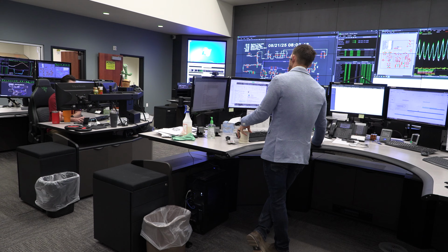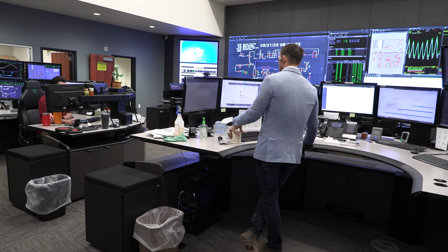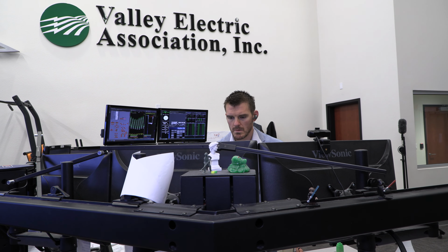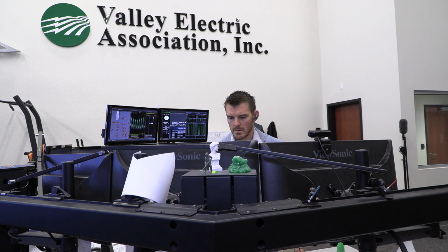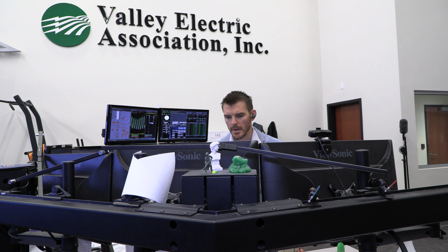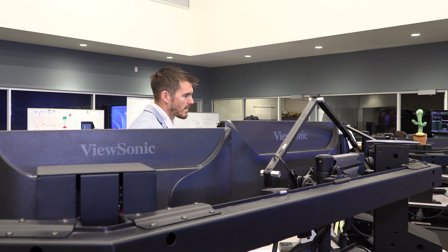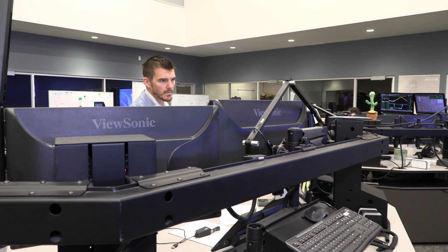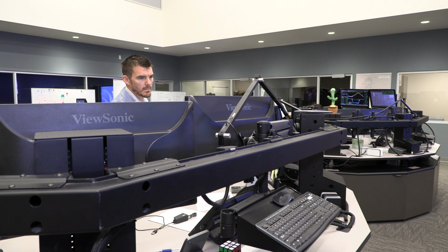It's separated in the fact that it has different outage severities. If we have a transmission outage, it's likely going to be more severe than a distribution system outage. If it's a very severe transmission system outage, it could encompass a lot of distribution that's out. A bad enough one could see the entire Plum Valley out, whereas with distribution you could see anywhere between 10 to a few hundred people, or even 1,000 people, depending on if it's a feeder breaker that opened at a substation or a field recloser that opened up.